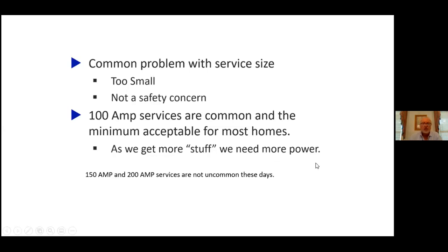Several homes over 3,000 square feet, you could easily have a 200 amp main panel, 150 amp or even 100 amp sub panel. If somebody, for instance, built their home and had an unfinished basement and they hadn't wired the unfinished basement, you would need more power if you had just a nice, perhaps a television room down there, a playroom, just a fun place to be.